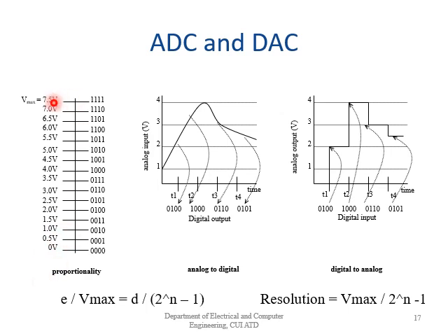Because our maximum voltage is 7.5, our minimum voltage is 0 volts, and there is a difference of 0.5 volts between every 2 consecutive levels. So you can use this formula. Resolution is equal to Vmax divided by 2 raised to the power 4, that is 4 bits, minus 1. So Vmax is 7.5, and 7.5 divided by 15 is going to be 0.5. So our resolution is 0.5.